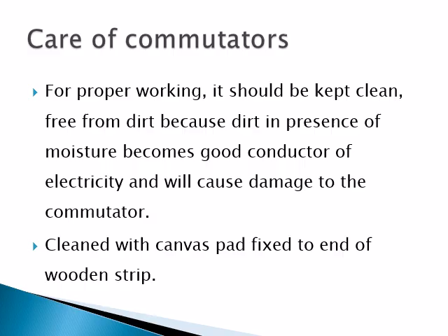Next is the testing of the commutator. For proper working, it should be kept clean, because when it is full of dirt or dust, in the presence of moisture, the dust along with the moisture will be a good conductor of electricity, and that will cause damage to the commutator. So it should be properly cleaned and it should be free from dust. Usually it is cleaned with the help of a canvas pad fixed to the end of a wooden strip.